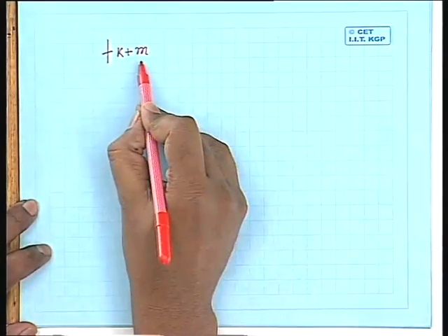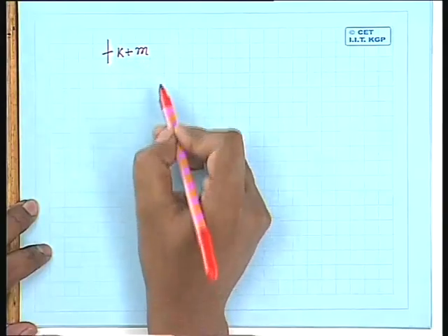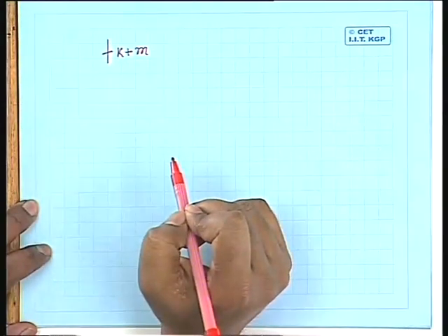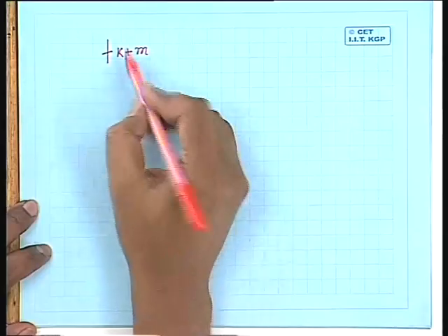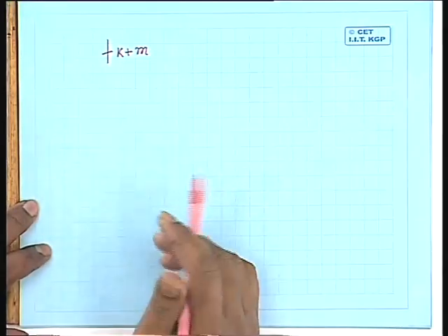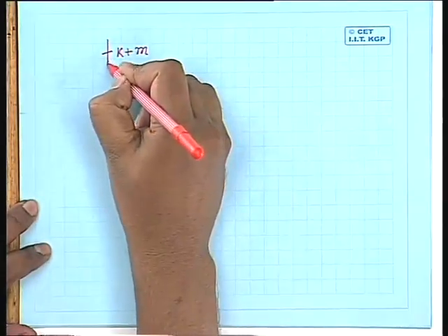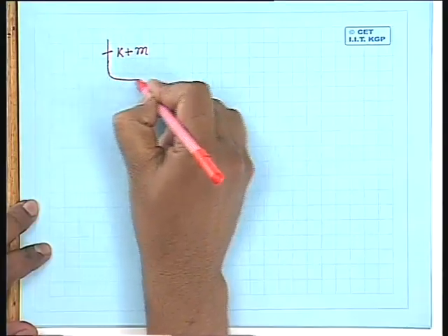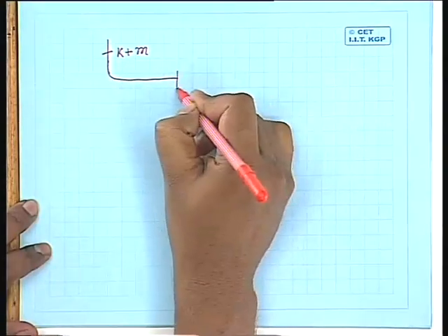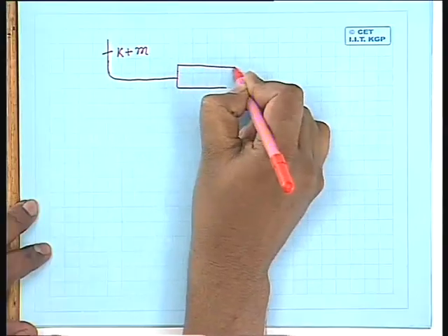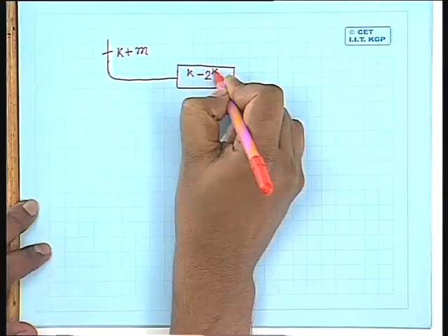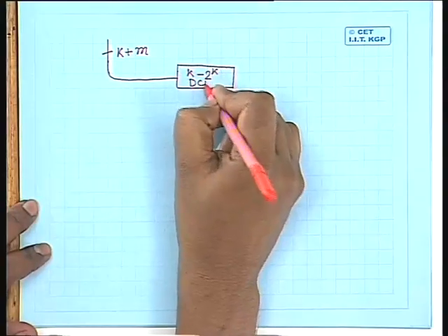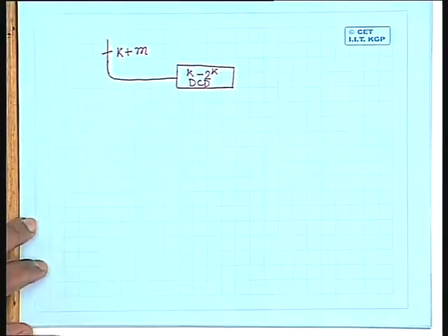Okay. M number of bits per chip gives you 2 to the power m number of locations. I want to connect 2 to the power k number of such chips in sequence. Okay. So total number of address lines becomes k plus m. Out of these k plus m address lines, the higher address k bit addresses I give to a k to 2 to the power k decoder. Right?